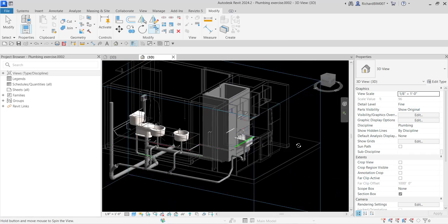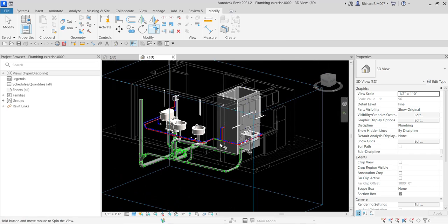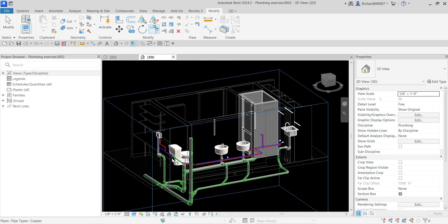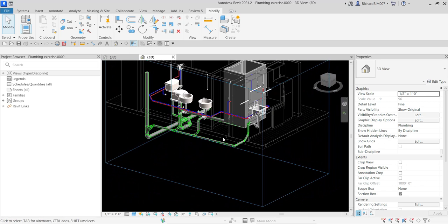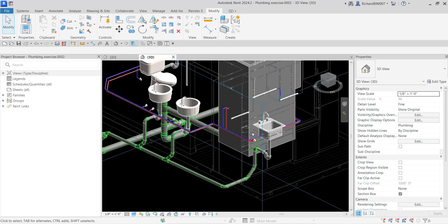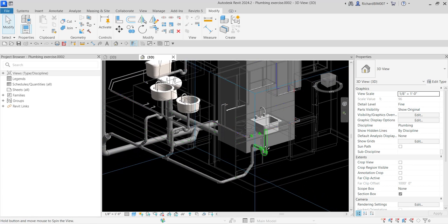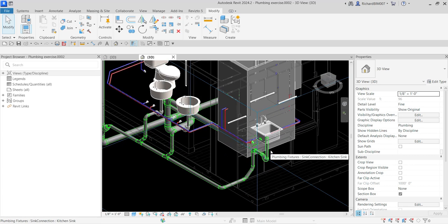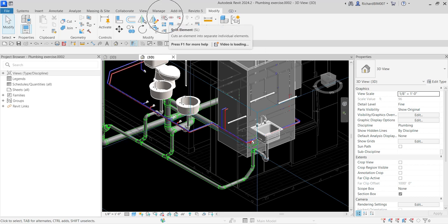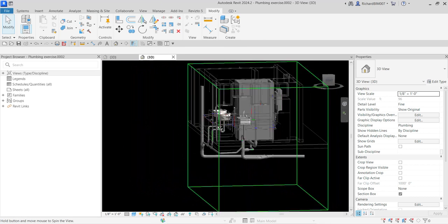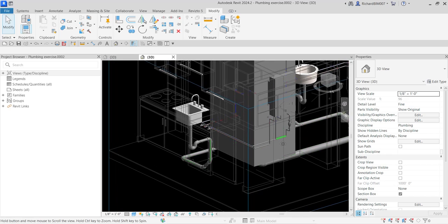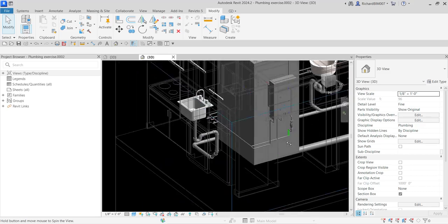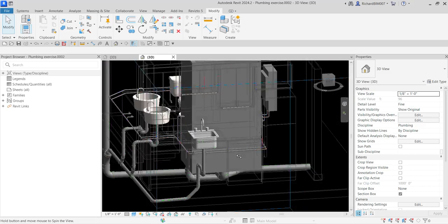Right. So basically, that's now the model of our sanitary and water connection. So as you can see, we have used different techniques on how to do our modeling. So if you have time, you can review this video and then just do whatever I did here, like changing the offset of the pipe, using trim, using split. Okay, so you will learn a lot in this video. So this is how I model. So these are just some of the techniques that I'm using in modeling my pipe.